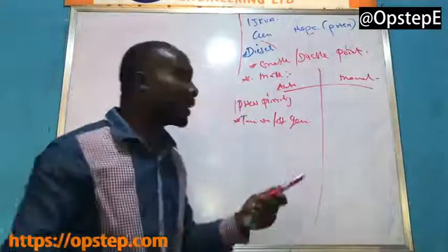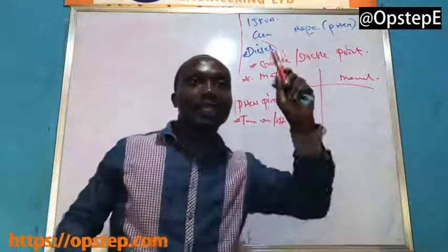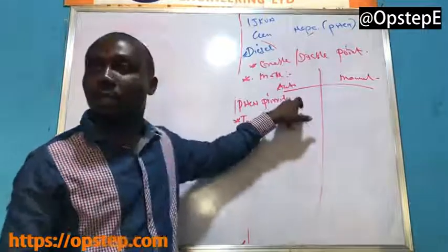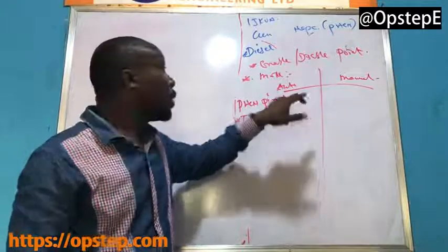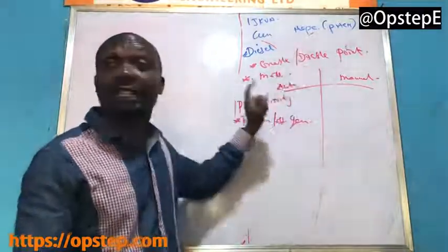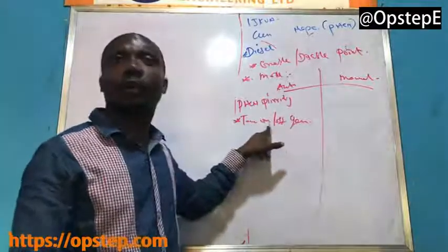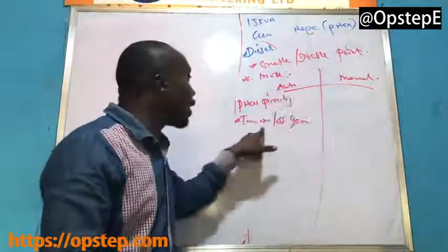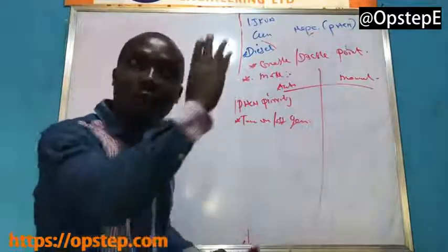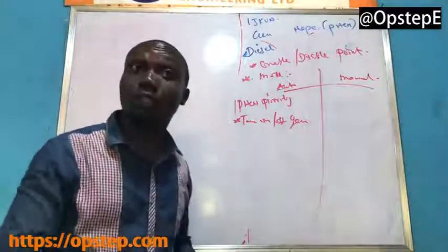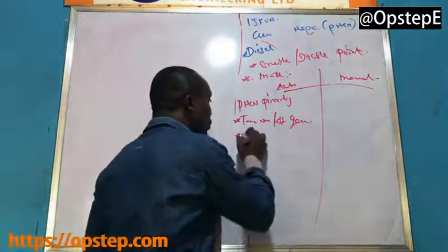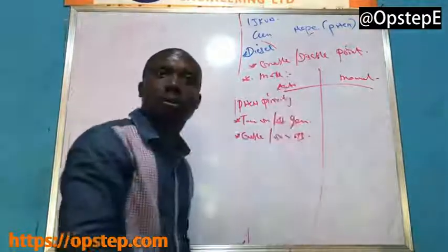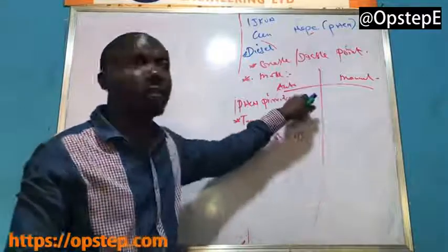The implication of this is that as long as it's in the auto mode, there will always be light in the house. Because if there's NEPA, it turns off the generator and puts the load on NEPA. When NEPA is off, it automatically senses that and then turns on the generator and supplies light. Now, as it's prioritizing NEPA, turning on and off the generator, the enable is also being set on automatically because it's in the auto mode. So the enable is on or off, depending on whether NEPA is available, or the generator is available.